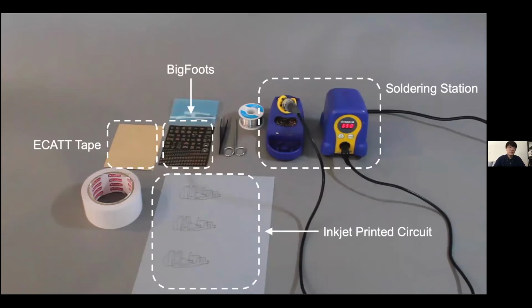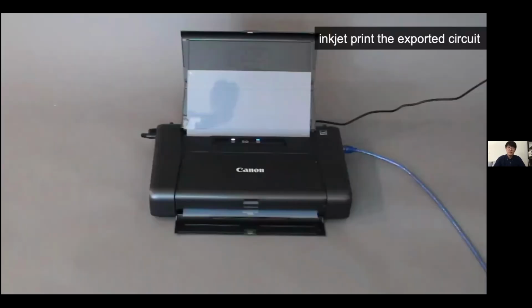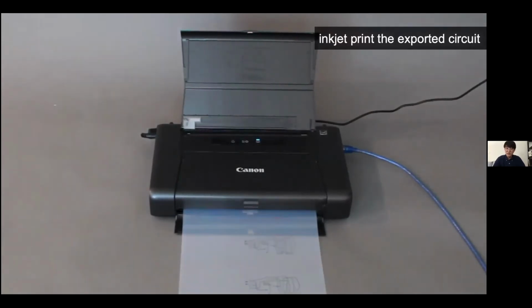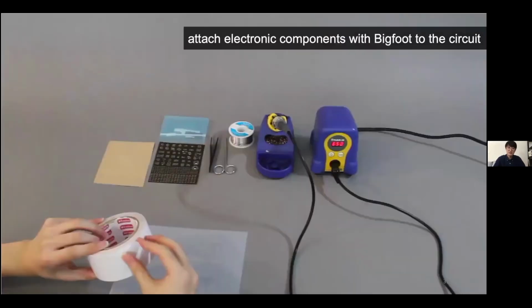Let me go through this in more detail. First, inkjet print the exported circuit. This is a normal office inkjet printer. All you have to do is empty the ink cartridge and fill it with silver nanoparticle ink. Then you can print out the circuit traces instantly.